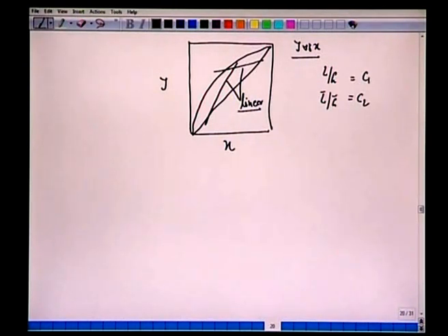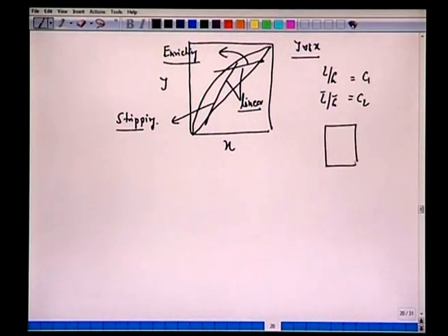So whether we have the operating line for the enriching or rectifying section, or the line for the stripping section or exhausting section, these two lines will be linear. And of course, just for the last time we say here that we are assuming that the enthalpy of the vapor and the enthalpy of the liquid are linear and parallel. In reality, of course, it will be like this. There will be some slant, but it's a very good assumption. Okay, now with that introduction, let's see how we can construct the number of stages.